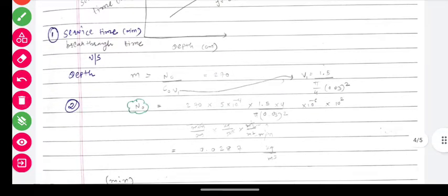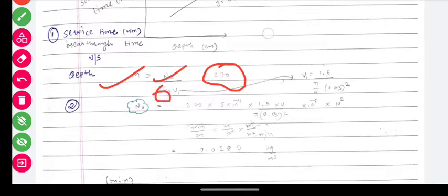Now you just equate both. This is your slope, and the slope value you know. N0 is unknown. C0 you know, it is given, I think it is 600. V1, the velocity, you will calculate as Q by A. Q is 1.5 for the first part of the calculation.